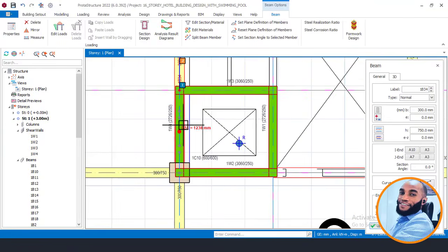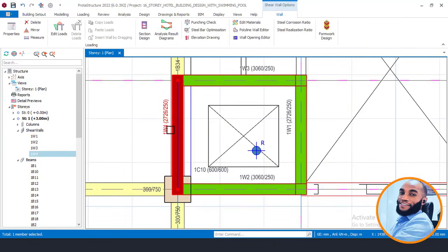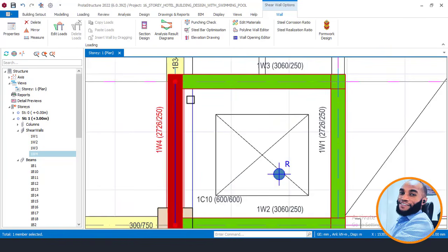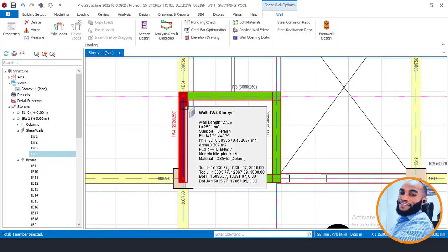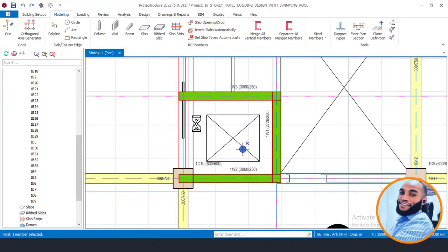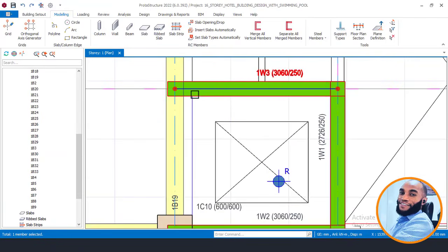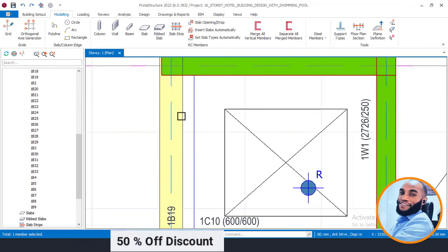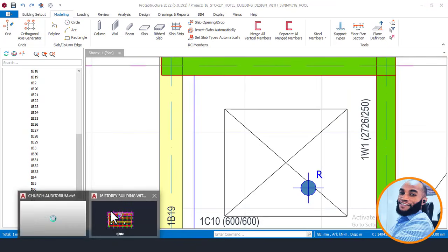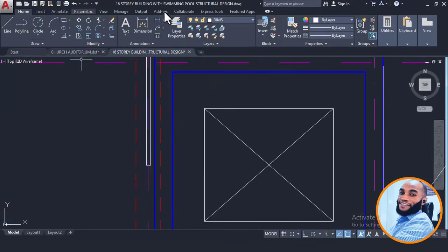Okay, now if I want to shift my beam off from that point, I'll have to do it something like this, because you can see that our wall here is placed directly around this place here. Okay, so I can do that just now by, okay, let me just undo first, undo, and make sure I follow what is directly there, undo everything. Okay, this wall here is meant to flush around this place here. Okay, so I'll have to place a grid line around this place here. So I'll have to go and check on my AutoCAD here, and check that difference. I'll have to place a line first from this point here to this point here.